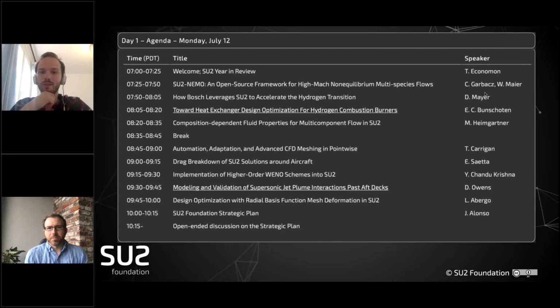Yeah, I think something related might be the type of solver you were using. So there's actually another question about that. I assume that in Fluent, were you using a pressure-based solver or density-based? Yeah, that's pressure-based. So yeah, that could explain some of the difference.